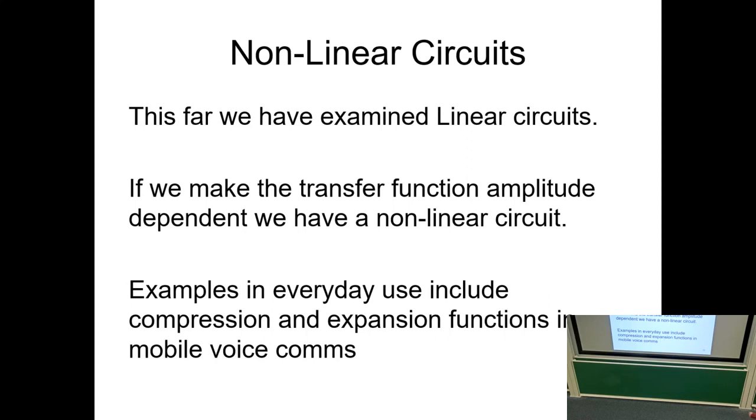Right, so those are linear circuits. Virtual earth theorem applies. Everything is nice and linear. We can apply mesh, we can apply nodal, we can apply superposition, which we've done today. So we've seen examples of that. And hopefully you can see that applying this superposition and some of this Kirchhoff's current law stuff, which is effectively nodal analysis, is actually very straightforward.